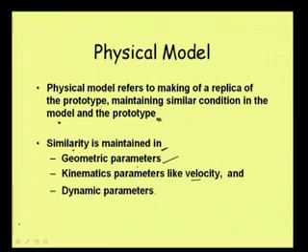Then there is another similarity, called dynamic similarity, or similarity in dynamic parameters, and that is very important for hydraulic model studies. Dynamic parameters mean we are talking about force. Say in a hydraulic problem where gravitational force is very significant, then the gravitational force exerted in the actual field must be the same as that in the model.